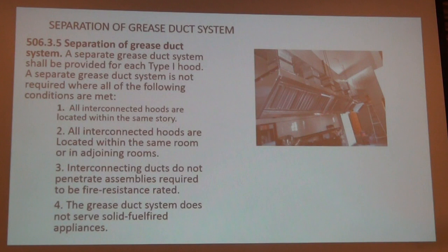It's weird. Here's that laundry list of the separation of grease ducts. It has to meet all these four things: all interconnected hoods located within the same story, all connected hoods within the same room or adjoining rooms, interconnected and do not penetrate fire-rated assemblies, and there is no solid fuel-fired hood.